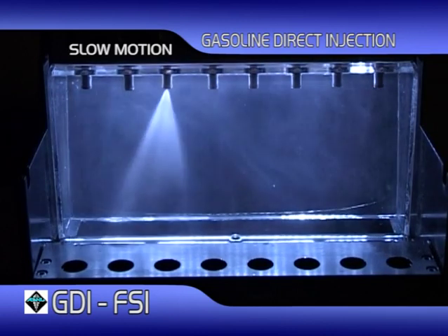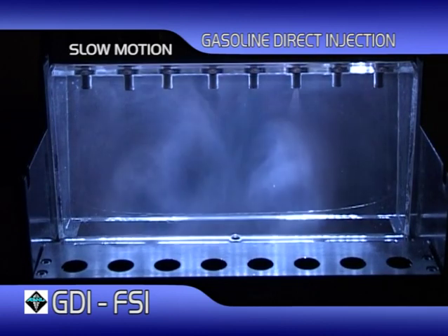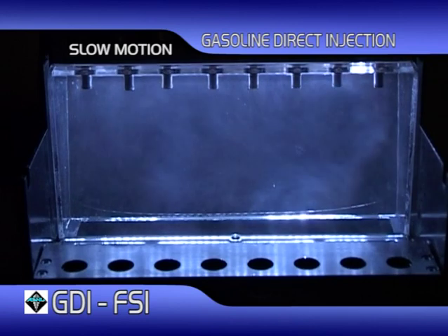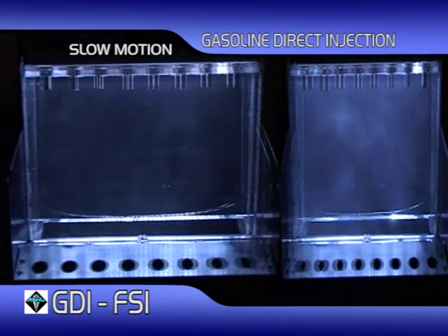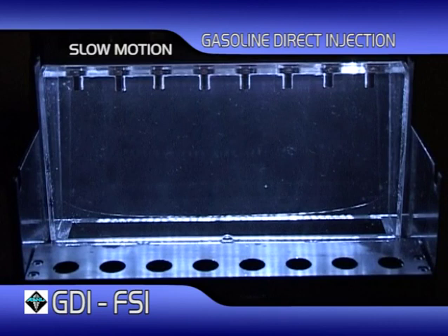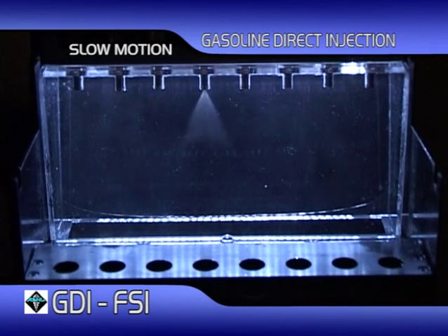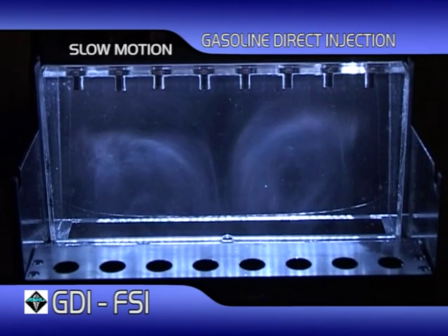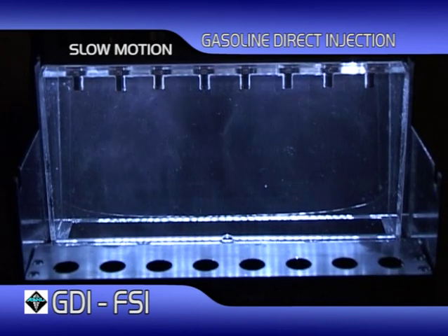Due to the amount of atomization caused by the injectors, it is easier to select single-cylinder operation to examine the injectors individually. As we select the individual cylinders, we can clearly see differences in the distribution and atomization of the injector's spray pattern. These spray patterns would cause differences in the air-fuel ratios, something that the lambda sensor would detect, but the problem will not be the lack or excess of fuel.